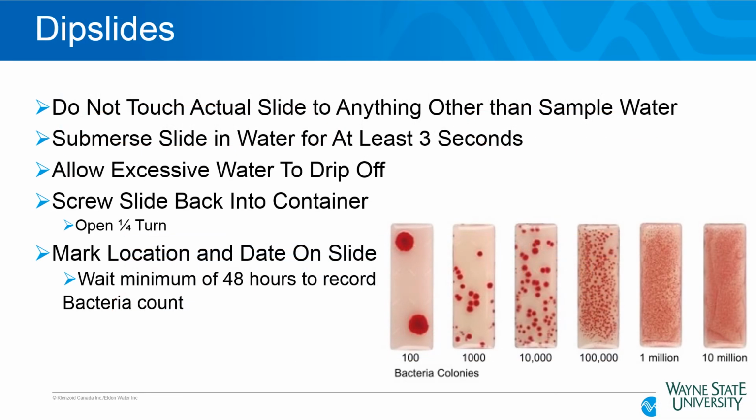More testing on dip slides once a week, Monday morning. Please take a dip slide, and just some best practices with this. Don't touch anything other than the sampled water with the dip slide. Any bacteria in your hands, surface, you lay it down on the table, it will completely screw up, and more often than not give you a much higher reading than is accurate.